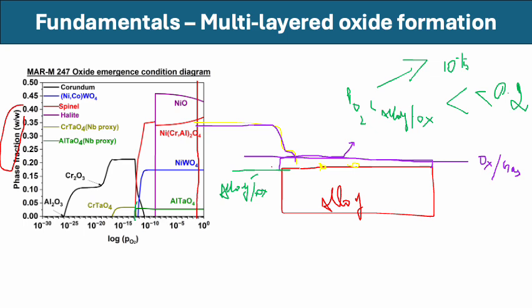So what will happen is that at this interface, I start to nucleate this blue color oxide, which represents this corundum phase, which is chromia. So this chromia particle grows and laterally grows, and at some point you form an internal scale. This is a second scale. Now the metal is gone, it has also become oxide, and this is a chromia oxide. This belongs to this oxide. Now this scale has formed.